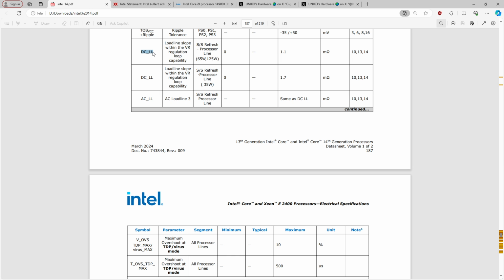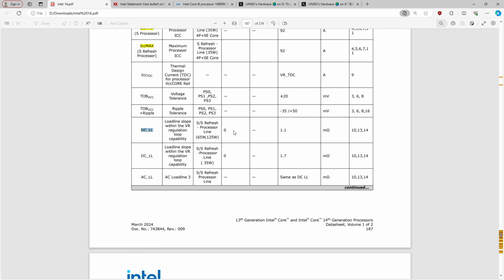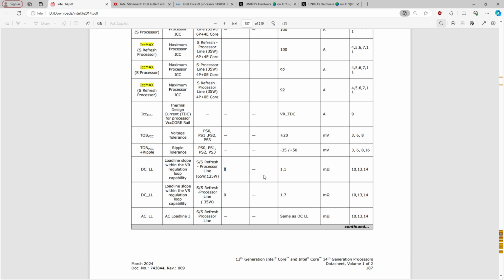The voltage measurement point is the sense points provided by Intel, and those are connected right before the silicon, or at the silicon, or maybe even somewhere inside the silicon. I don't know how Intel wires in the sense points. So this being 0, I feel like it should have a minimum value of whatever the CPU substrate and socket load line work out to be on their own.